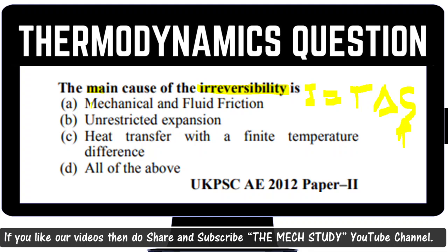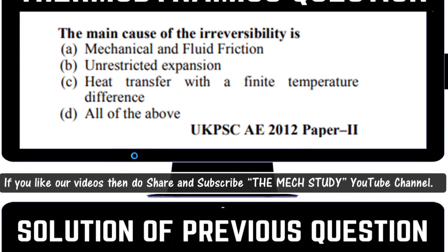So they have mentioned the main cause of irreversibility. The first option was mechanical and fluid friction. This is right, because irreversibility is caused due to mechanical and fluid friction. Due to this, heat is generated. Unrestricted expansion is also a cause of irreversibility. Heat transfer with a finite temperature difference, if these two are right, then definitely this is also right. Due to this there is also an increase in irreversibility. So if all three are right, then option D is the right option for these types of questions.